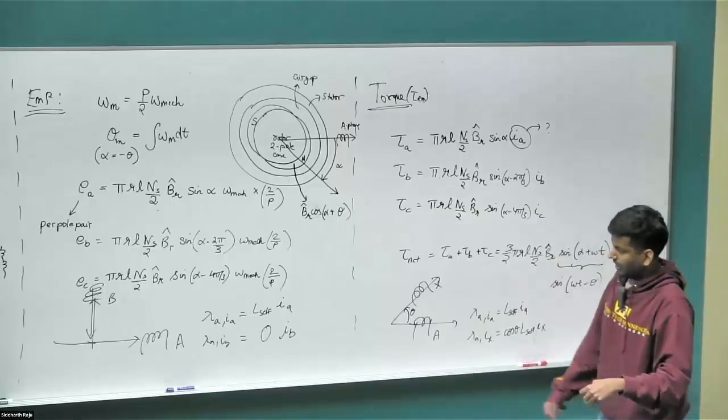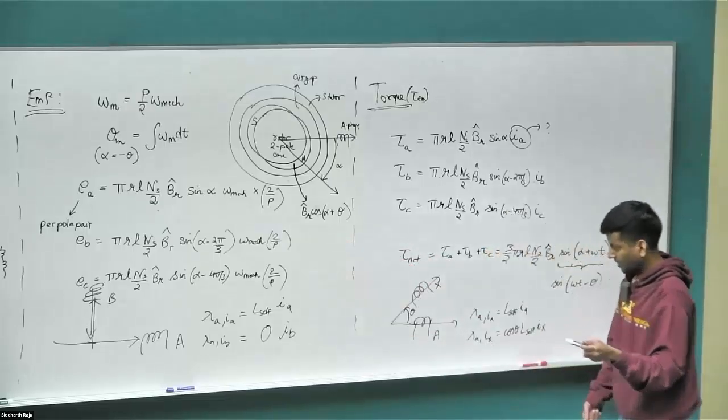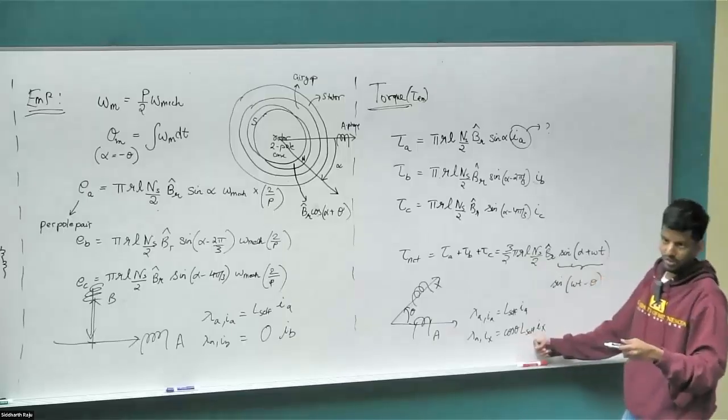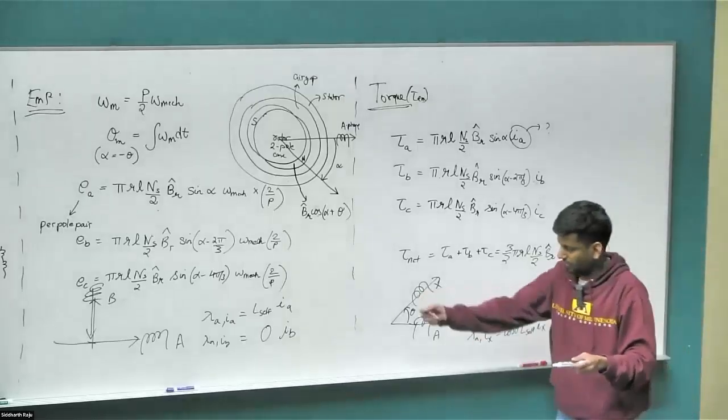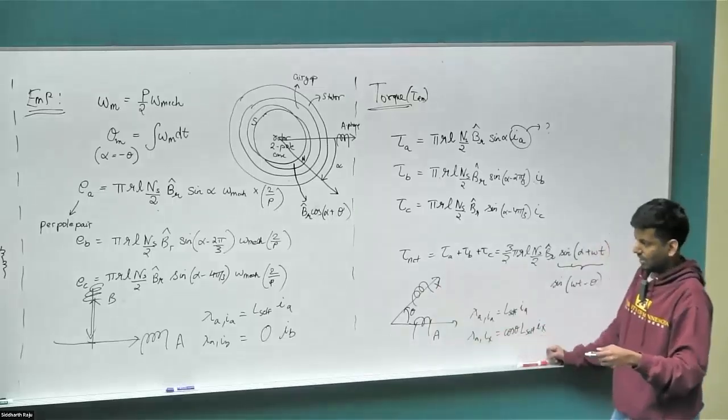So we derived it for the case where the windings were 120-degree phase shifted in our lecture, and this cos of 120 ended up coming out to be -1/2, and that's how we have -1/2 times L self. If you have 90 degrees, that will end up being 0. If you have some other angle, that will end up being cos of theta times L self.